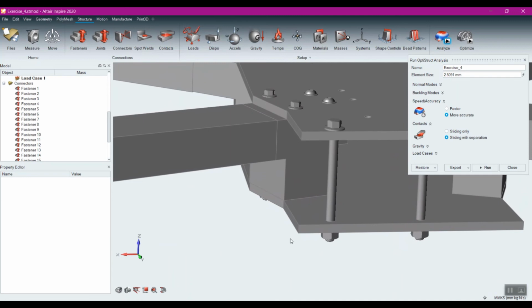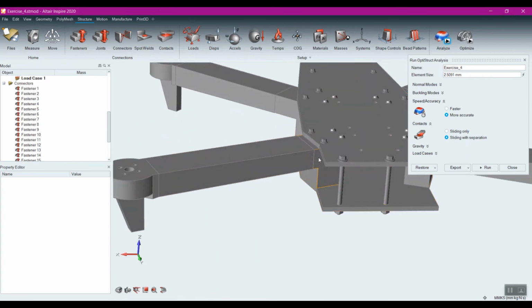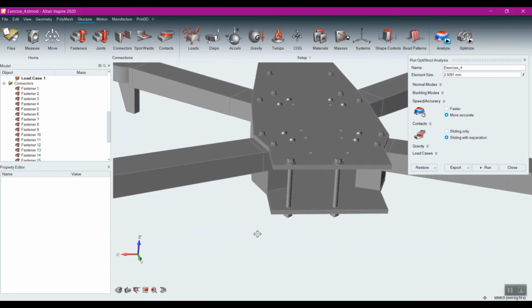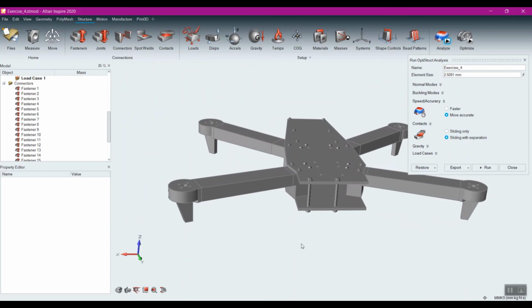The reason why it's not on by default, and the one slight downside to it, is constantly then calculating or taking a look at the forces in the areas of contacting surfaces. I've only got 8 of them on this model, so it would not affect the analysis time too much in this case, or barely at all. But if you had many, many contacting surfaces in your model, it could potentially increase the analysis time.